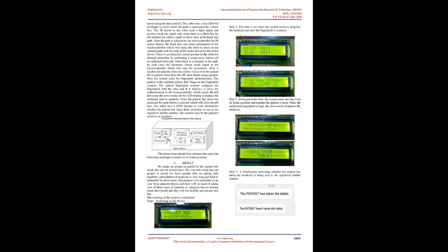Arduino is programmed in such a way that when the current time matches the time which is already set in the real-time clock, it sends the control to the audio amplifier where the alarm gets activated and gives a voice note of which session it is. The alarm rings until the user or patient presses the button. If the patient presses the button, automatically the pill for the corresponding session comes out.